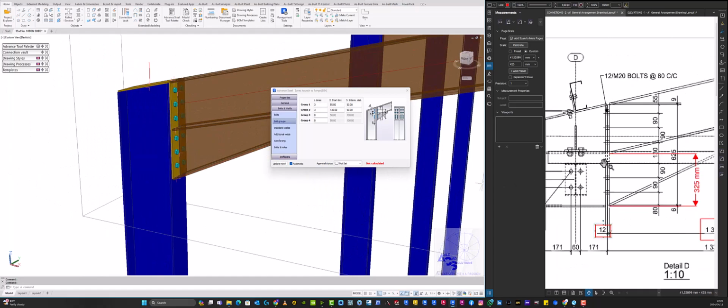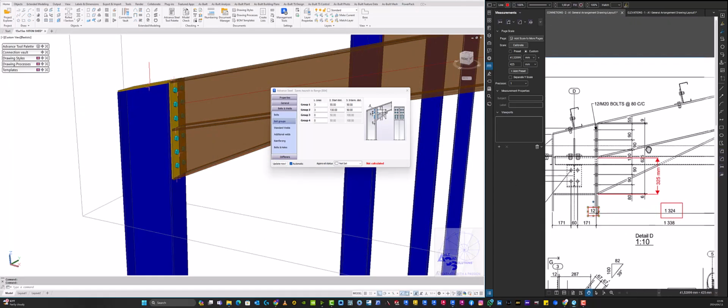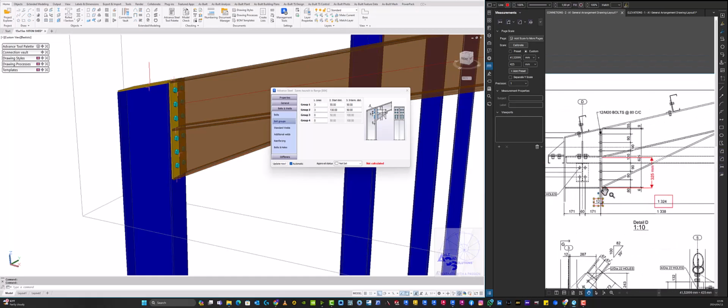Then from there, we add our stiffener on the column. This stiffener on the column comes with this connection. So we can standard weld 6 millimeters. That's what we want. If you've got welding preferences, this is where you change. Additional welds, you can add them there. Reinforcement plates, you can change them there. We don't need to worry about that because it's not part of the scope. Bolts and holes, we don't need to. You can either make the hole slotted, it's up to you, but here we don't need to worry about that.